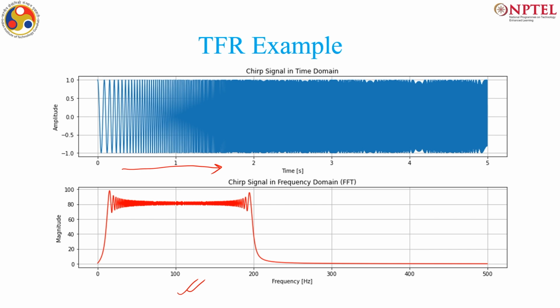And from this it is very difficult to identify that this is composed of not only these many frequencies, but these frequencies are happening separately at different time locations, like this is a high frequency region and this is a low frequency region. In this kind of signal, time frequency analysis is very useful, because with just the time domain I do not know what the frequencies are, and in the frequency domain I do not know where they are occurring, because this is a flat spectra which denotes an impulse kind of thing, but actually it is something entirely different.